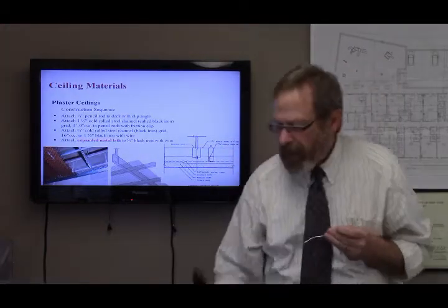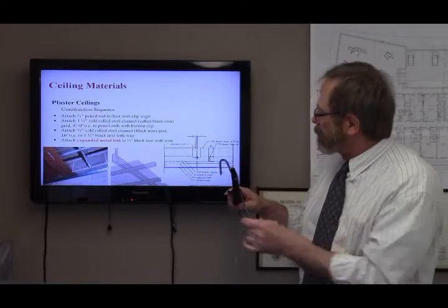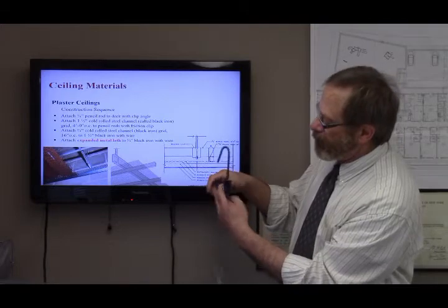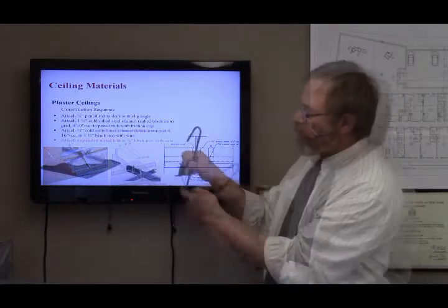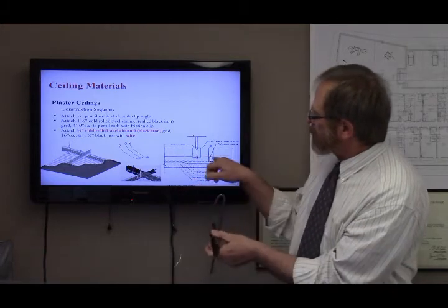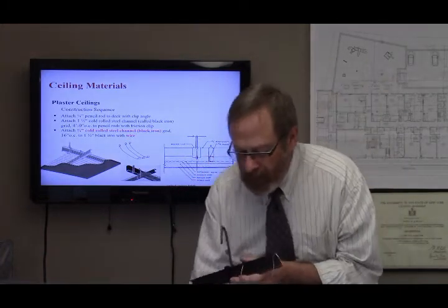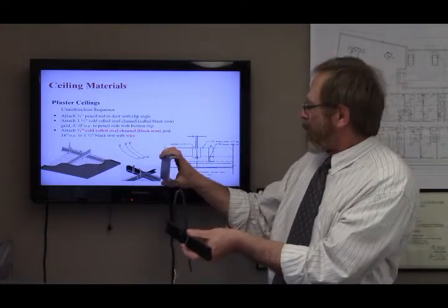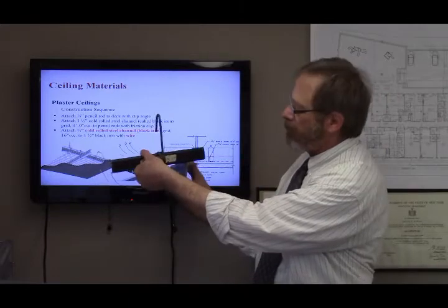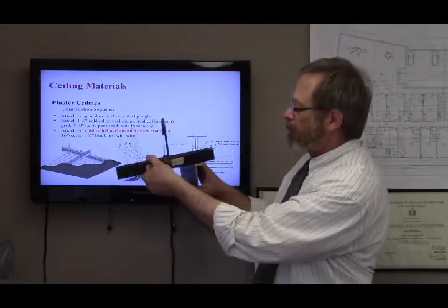We're going to tie a 3/4 inch black iron metal channel, 16 inches on center, to the bottom of this metal channel, tie it around the first channel and hang from it a smaller 3/4 inch black iron piece. I don't have a small one. This is a big one, obviously way bigger than what we need. But this would hang from here, supported by the metal wire.